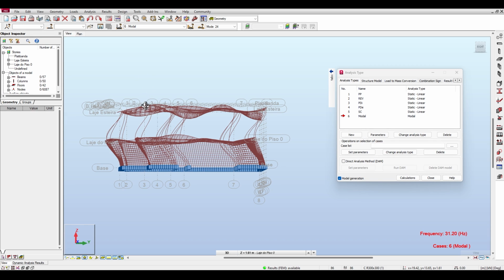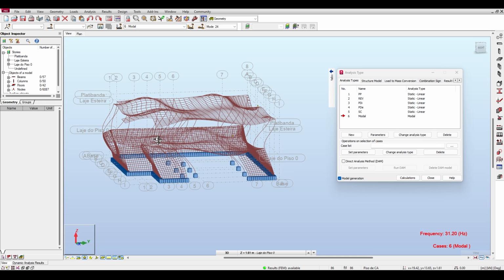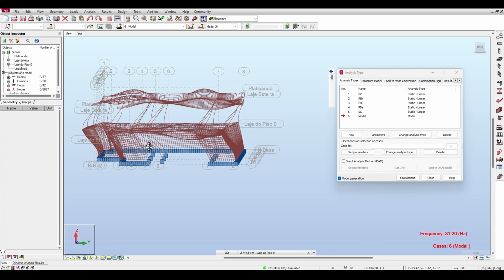Furthermore, it seems, and this is the third time I see this in action, that the structures are harder to vibrate in Z. The reason why they are harder to vibrate in Z is because of the axial stiffness. Why would a structure vibrate in Z? A structure would vibrate in Z if the slab vibrates or the walls vibrate. Now the slab vibrating in the Z means bending of the slab, and the stiffness of bending can be vibrated. However, other things related to vibration in Z are the axial stiffness of those walls. And there is no way you can vibrate those walls in the Z axis. They are just too stiff. You would reach mode 600 and you are still not able to vibrate those walls in the Z axis.